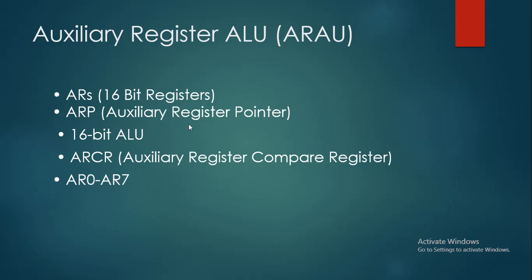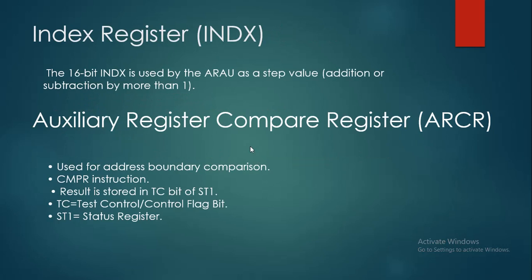Next, it consists of the block move address register, BMAR, which is also a 16-bit register. It holds the address value of the source or destination space of a block move. The BMAR can also hold the address of an operand in program memory for a multiply accumulate operation.